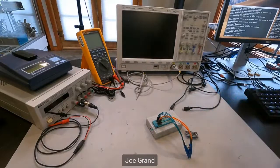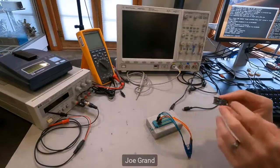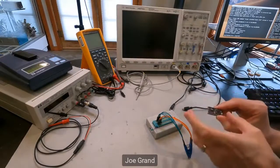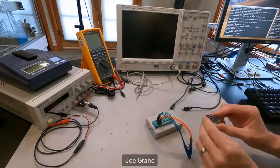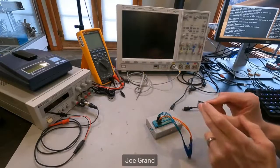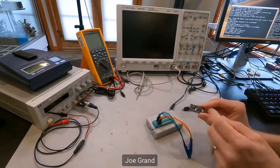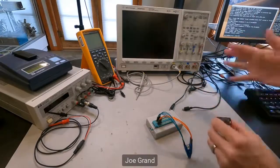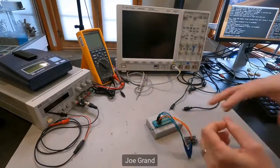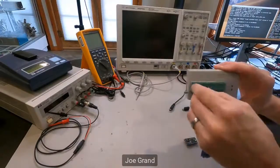And generally we can, as long as there's no bus contention, basically meaning as long as nothing else is trying to read that memory at the same time, we'll be able to connect to it and get the contents off. And like I mentioned, generally systems are going to read that device on power-up. We can just wait till the system boots up and then read the code off. If it's something where the system is constantly talking to it, then we have to do some tricks of maybe disabling the clock or holding the device in reset or whatever, which is a talk for another day.